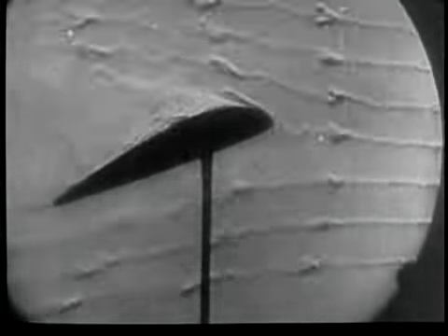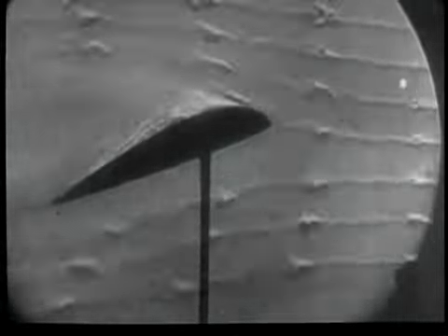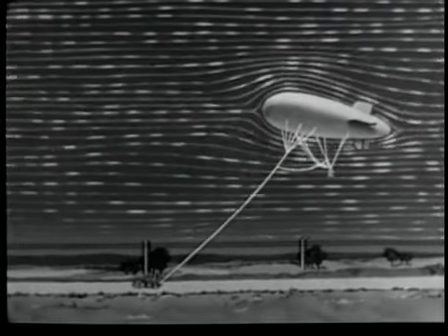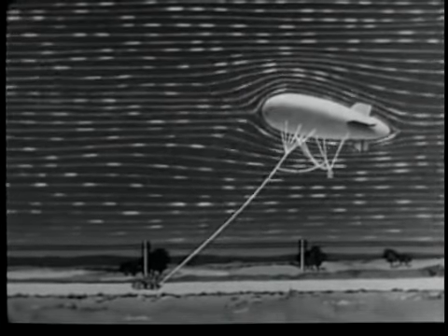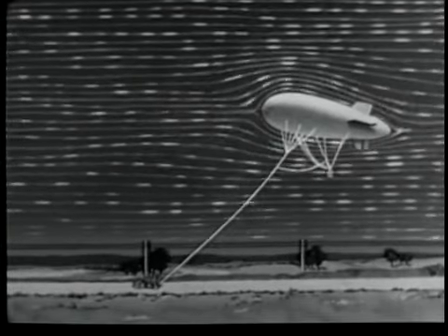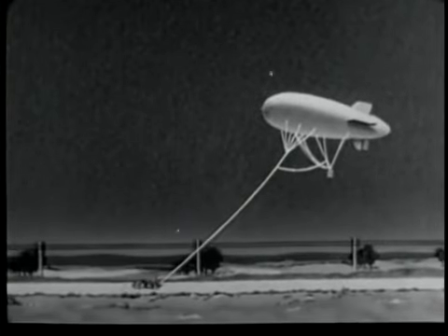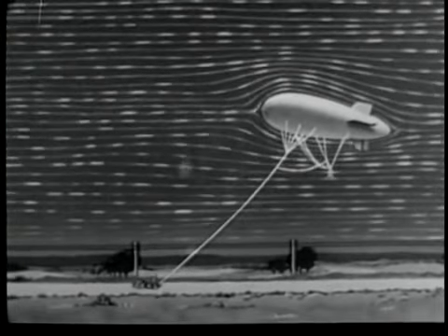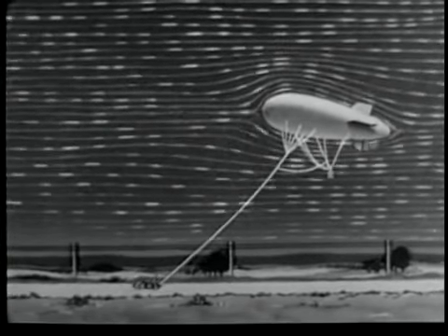Aerodynamics treats of the motion of air or other gases and of the forces acting on solids in motion relative to such air or other gases. Relative wind is the motion of the air with reference to a body. It may be the result of moving air and a stationary body, or still air and a moving body, or both air and body may be moving with reference to the earth. In this case, the relative wind is the algebraic sum of the two motions.